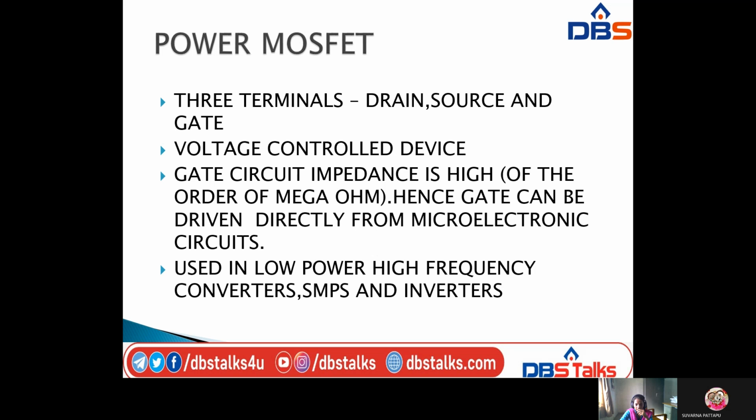The gate circuit impedance is high, of the order of mega ohms, so it will be very high. Hence, the gate can be driven directly from the microelectronic circuit. It is used in low power and high frequency converters, SMPS and inverters. So MOSFET will have three terminals: drain, source, and gate.